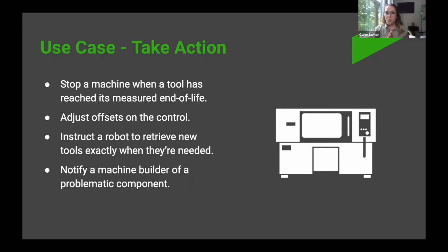Super interesting. Okay, another cool one came through. How much of predictive algorithms on machine metrics is related to machine maintenance against process performance? Interesting. So when you think of predictive, at least in the sensor space, you need consistency in order to get enough data points to be able to recognize a pattern. And it's really common in things like wind turbines or aircraft engines where you have that very consistent process. With CNC equipment in particular, there's so much change that the problem is actually very challenging. To answer the question directly, most of our stuff is more based on maintenance and tool breakage.